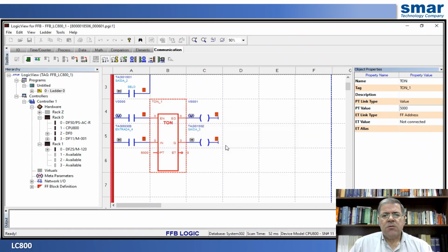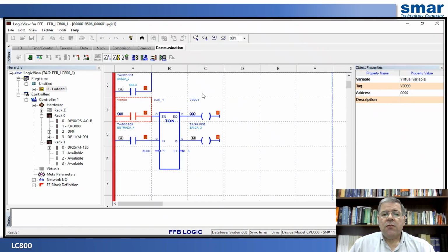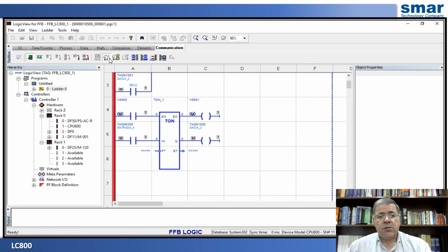It brings up the entire configuration of the block's parameters, and you can modify online the execution time of this timer. As with the other blocks, such as PID configuration, we can also tune the PID, we can modify a set point, we can modify the entire configuration by pressing this button, and in the menu on the right-hand side, you can make changes online. I am now going to make a new change to the project.